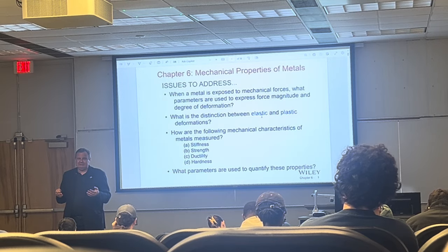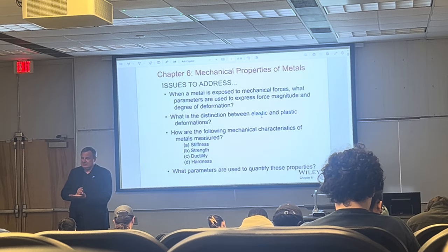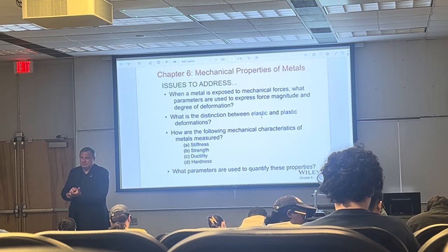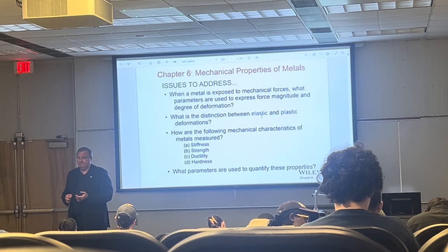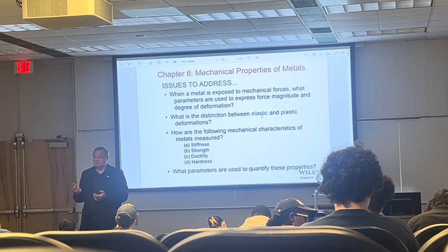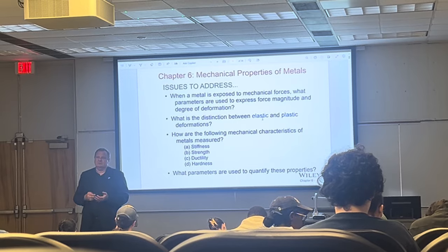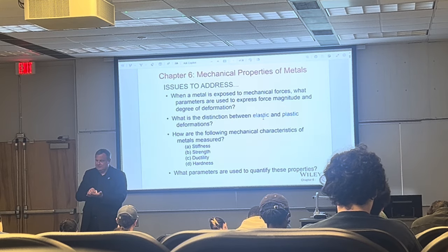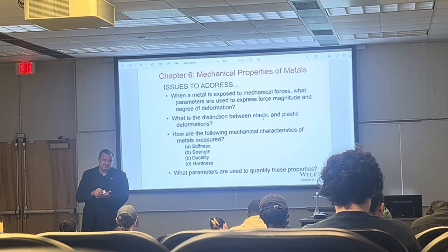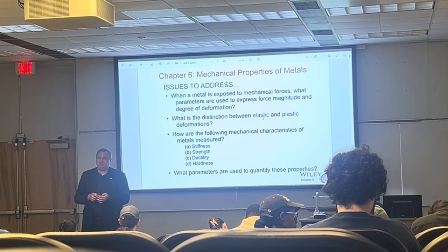Interruption in a pattern. Okay, what kind of interruption in a pattern? Extra half a plane. And to induce a dislocation, what kind of stress do we need to apply? Strain, stress, what kind? There's normal and then there's shear. Shear. So we introduce shear stress, right? And we introduce that half a plane, or if it's an edge dislocation or screw dislocation, doesn't matter. The idea is the same. And eventually this dislocation is going to travel and emerge at the surface, right? Which gives us persistent slip bands.